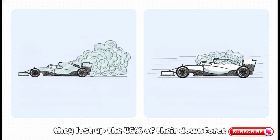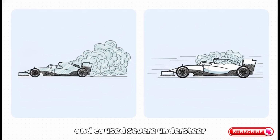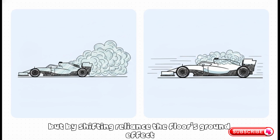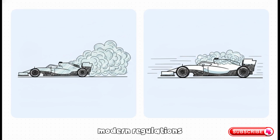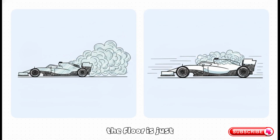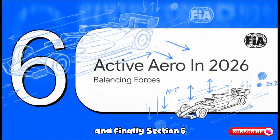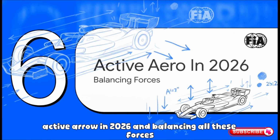Pre-2022 designs relied super heavily on complex upper body wings, and when they hit that dirty air, they lost up to 46% of their downforce. It made following incredibly hard and caused severe understeer. But by shifting reliance to the floor's ground effect, modern regulations miraculously slash that loss down to just 10%. The floor is just way less sensitive to that turbulent wake. And finally, Section 6, Active Aero in 2026 and balancing all these forces.